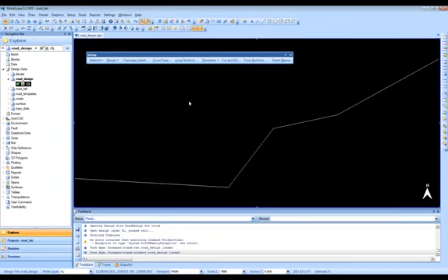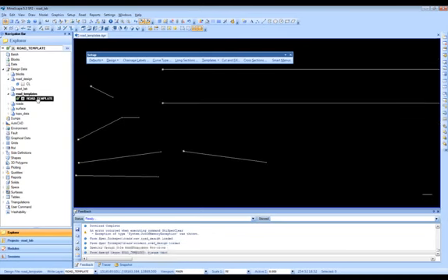And then we do have a template setup. Under templates, you can create templates, edit templates, and tag templates. These template functions are really to set up what the cross-section looks like for this road design. So you might have a crown road, you might have some super elevation, etc. As I mentioned to you, I have a road design template, road templates, design file, and road template. So I'm just going to go over there real quick and open that up.